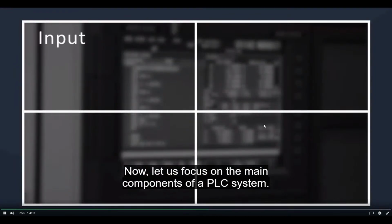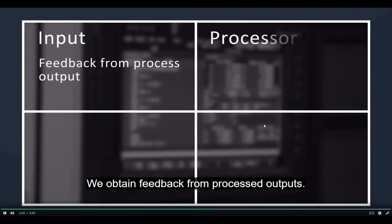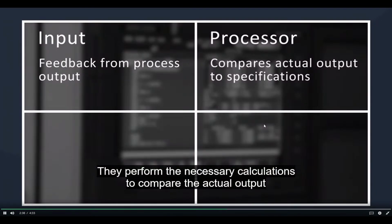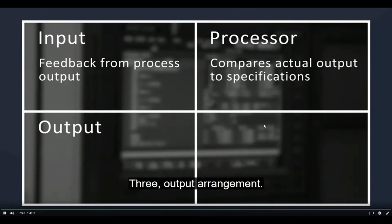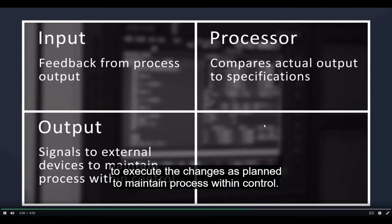First, input arrangement. They obtain feedback from process outputs. Two, processors. They perform the necessary calculations to compare the actual output against specification to arrive at changes required to the inputs. Three, output arrangement. They provide signals to external devices such as robotic arms that will be used to execute the changes as planned to maintain the process within control. And finally, the power supply, which powers the overall PLC system.